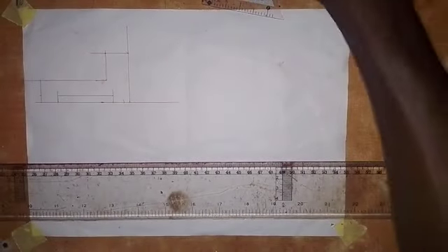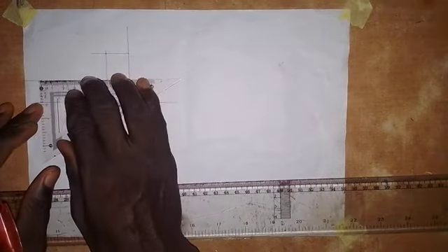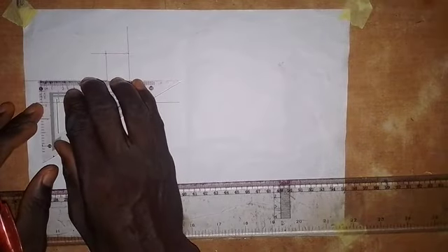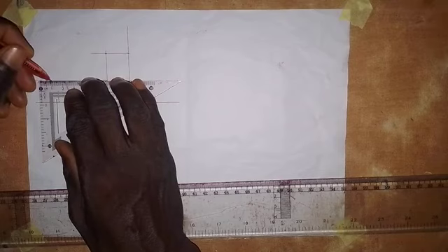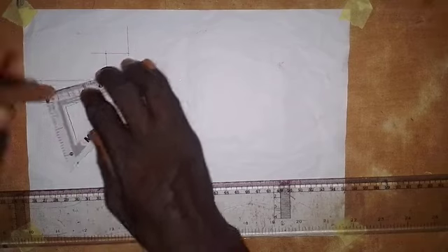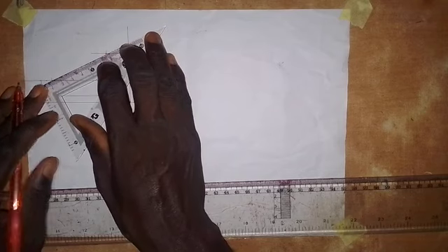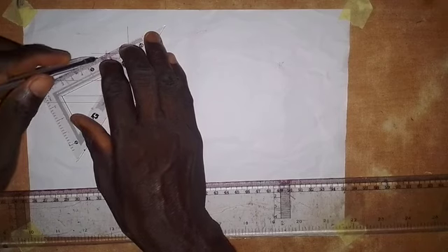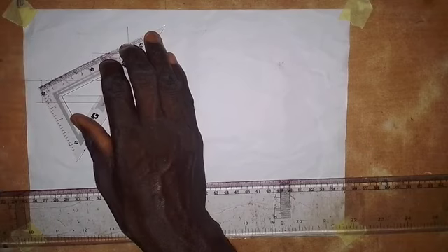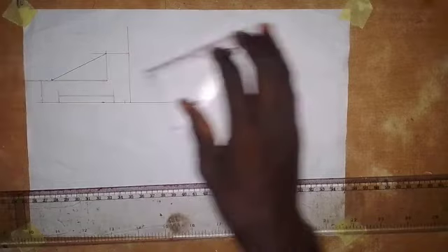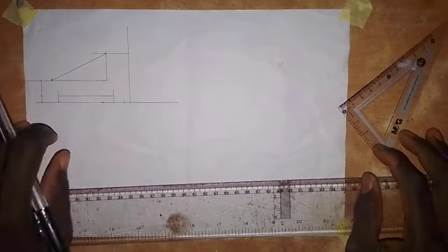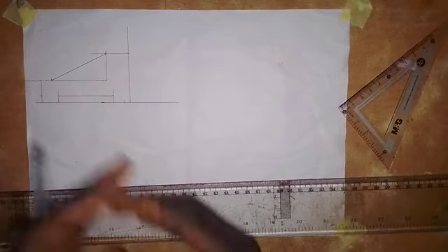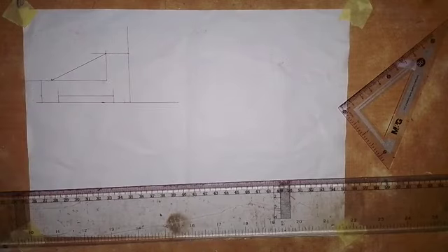So what I need to do now is to come to this front face here, and I will take 10 millimeters inward. So this is 10 millimeters. And I will join these 2 points together, making it a thick line at once. So this will be the elevation of the web. The next thing we need to do is make this line thick before we do the arching of this surface. So I'll pause the video and quickly do that.